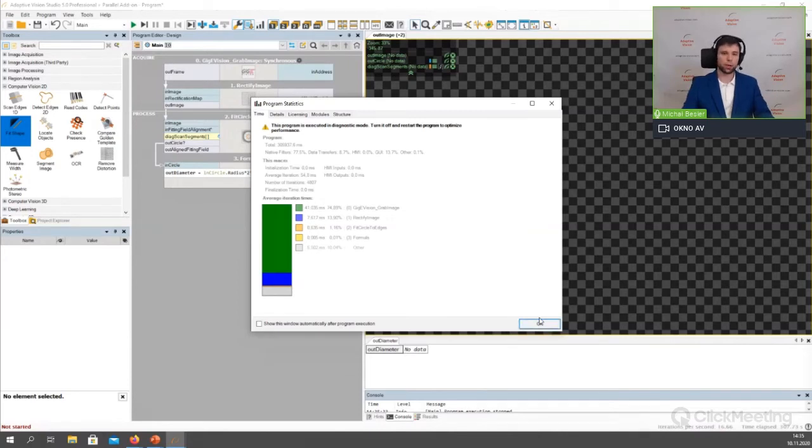In fact, it is because during the calibration process, we are creating something which is called the rectification map. So finally, once the calibration is done, each image is only rectified. We have information where each pixel should be repositioned. So we are just moving the pixels from the input image to their desired locations. That's why this process is so extremely fast.